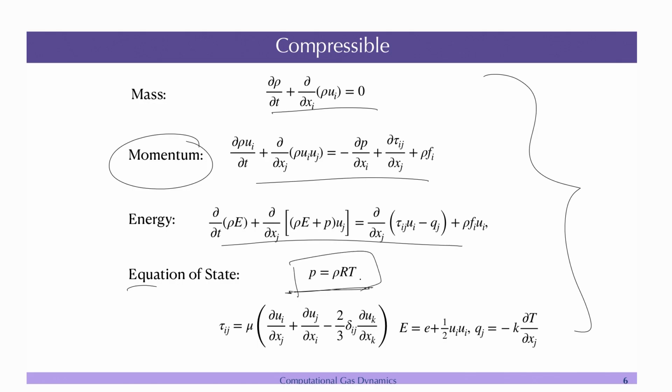You can have, let us say you want to do it for a flow which is different than an ideal gas, you will have to find an equation of state for that particular thing. Okay. And then we have the constitutive relation that I was talking about. This is for the Newtonian flow. Okay. Compressible, if it is incompressible, you know that del dot u goes to 0, it also gets simplified, and then we have energy diffusion and thermal conductivity which is coming in.